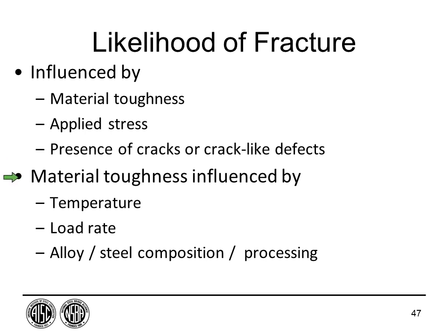Now the material itself, its toughness, unfortunately also is influenced by a number of things. One of the big ones is temperature. And you can illustrate this with a piece of gum. If you had it in your pocket all day, it's quite ductile. If you put it in the freezer, it becomes brittle. Well, steel, especially older steels, can be susceptible to that. At low temperature, they become more brittle. So temperature influences toughness. How fast we load the specimen influences the toughness. And of course, the steel itself, the alloy, the process, how it's composed, and so forth.